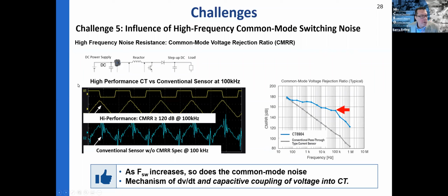In fact, with the agricultural tractor inverter that I mentioned earlier, this was exactly what was happening. The problem is we had a 2 megasample per second sample rate, so we didn't see this in our current waveform.